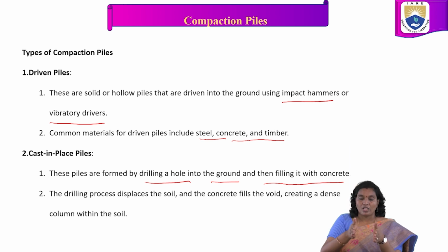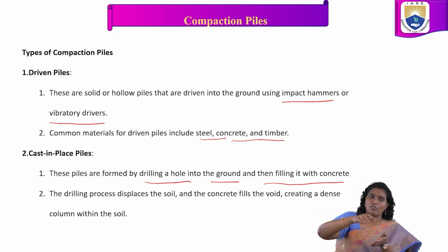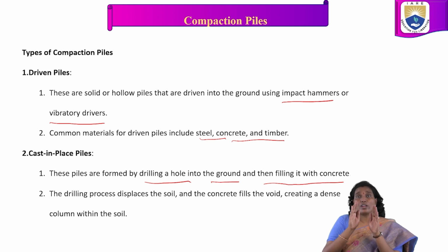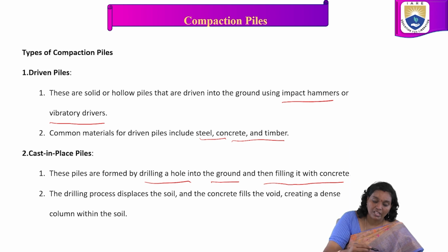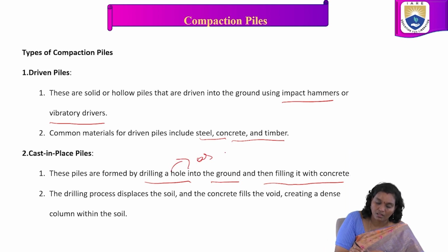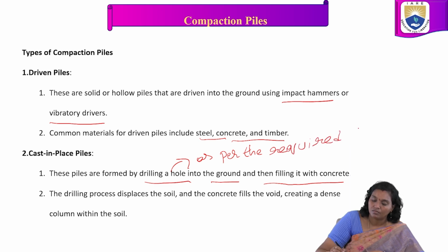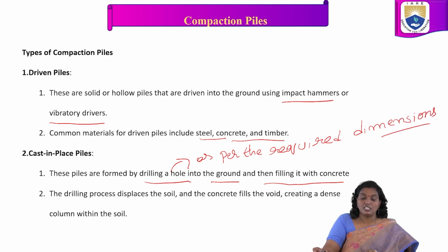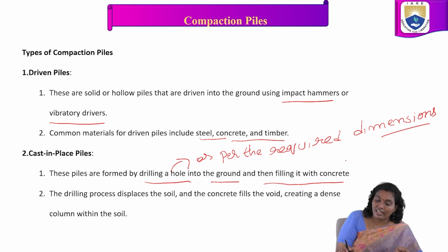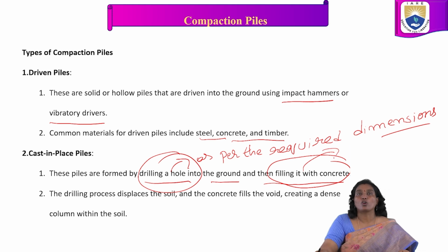Based on how much depth and how much diameter, we are going to drill a hole into the ground as per the required dimensions. Then once the hole drilling is done, we are going to fill it with concrete.